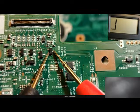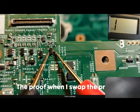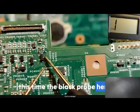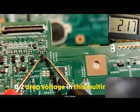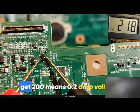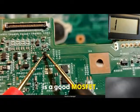Means what? Means this MOSFET is N-channel. The proof: I swap the probes. This time the black probe here on the drain, the red probe on the source, we get already about 0.2 drop voltage. In this multimeter, I get 200, 0.2 drop voltage. Which means this is a good MOSFET.